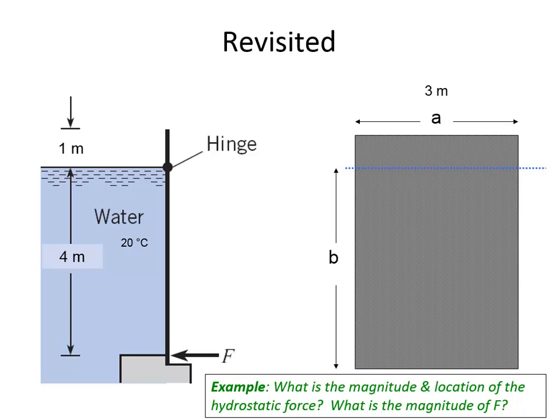So you find out what is delta H, what is Y bar, what is YCP, then calculate the pressure at the centroid, then calculate the hydrostatic force. And once you go through that process, then you'll know the location of the force and its magnitude. All right, so I'm going to give you a couple of minutes. Consult with the people sitting near you if you get stuck. But delta H is the distance to the centroid.